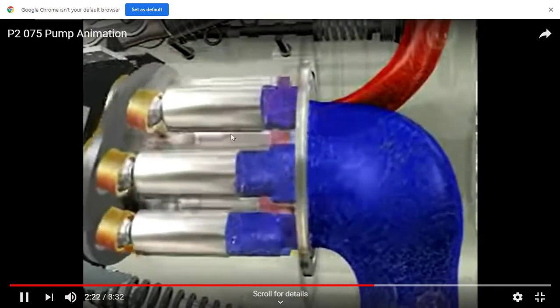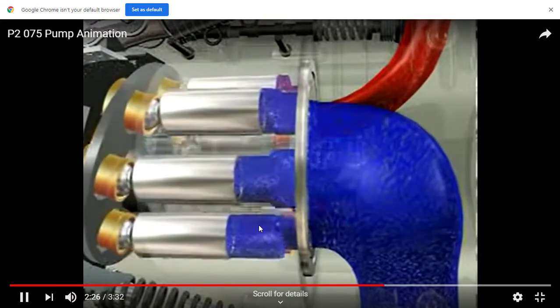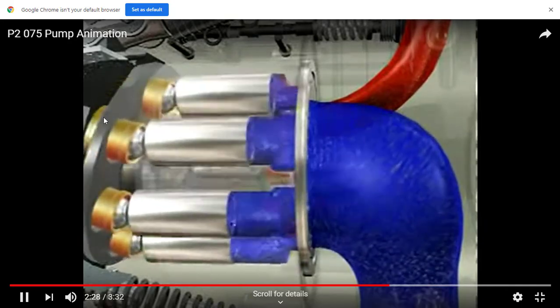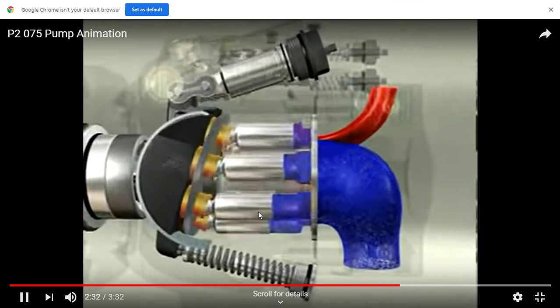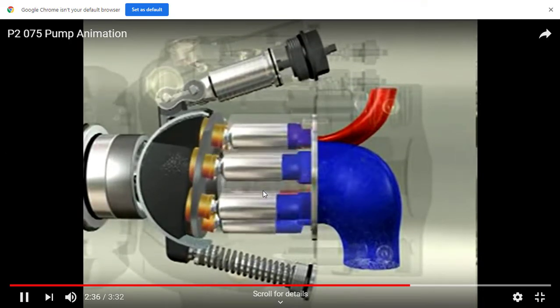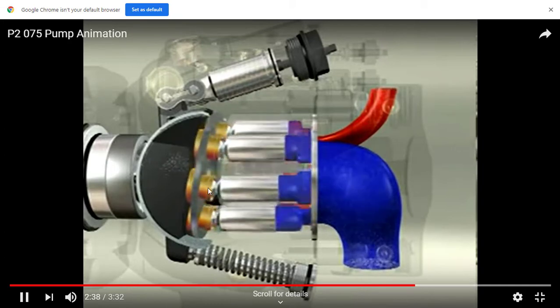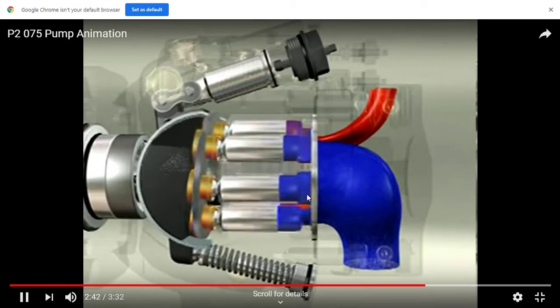The angle of that swash plate determines what your flow is. Sometimes you can't control the engine RPM. So by putting that gray swash plate at a steep angle, the pistons go way down in their bores and pull in a lot of fluid. If you don't need flow, but the engine's got to keep running, you can straighten out that swash plate, make it more vertical, and you can see the pistons don't go so far down in their bores.